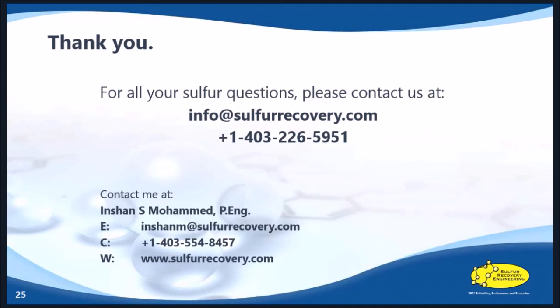So do I see a definite change? The answer to that question is yes, you'll see a change. If the incident has done something to the catalyst, you will see a change. And that's why we always recommend, once you do a sulfur wash, you'll want to make sure of two things. Number one, you want to make sure that it solved your problems. And number two, you want to make sure that the incident itself didn't affect your SRU. Great question. Hope that helps out a lot of people who may have been thinking about that.